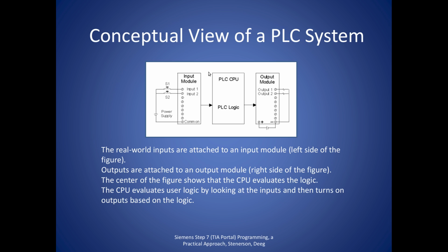After all those assignments are complete, then the ladder logic program is executed. And this program only manipulates bits in memory. It doesn't change physical values. So if an output is to be set true, then a 1 is assigned to that memory bit. After all the instructions in the ladder logic program have been executed, then again the bits in the output memory are mapped to the physical values. So a 1 would give you a high voltage, or an on, on that output, and a 0 would make that output off.